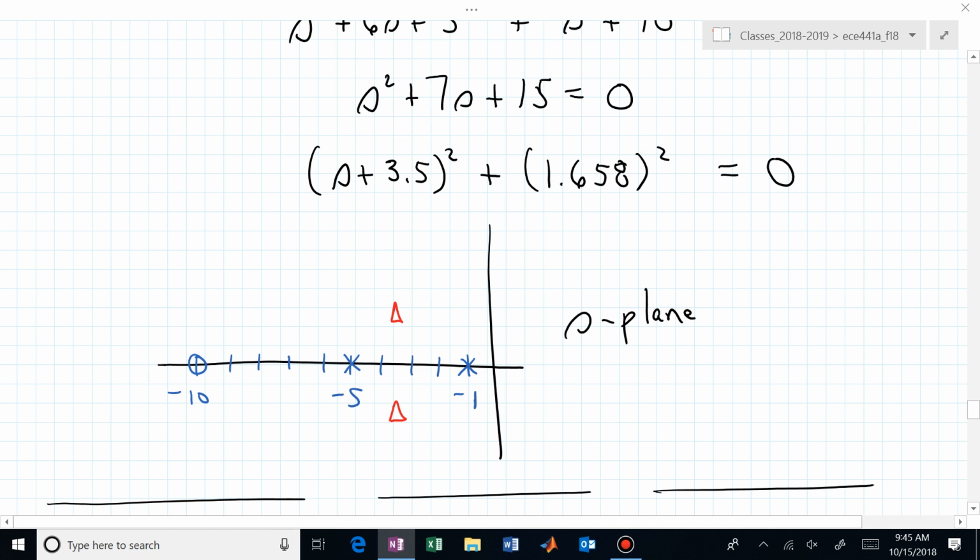And now they've both shifted over, and they're complex conjugates, they have the same real part. They're at minus 3.5. We're almost at our settling time spec, aren't we? For a K of 1. We needed those real parts to be at minus 4, and they're at minus 3.5.